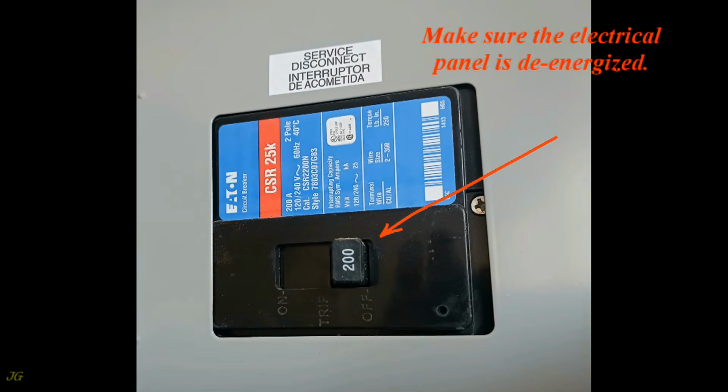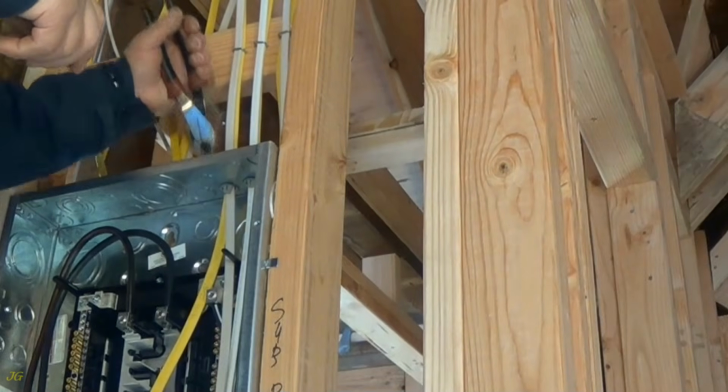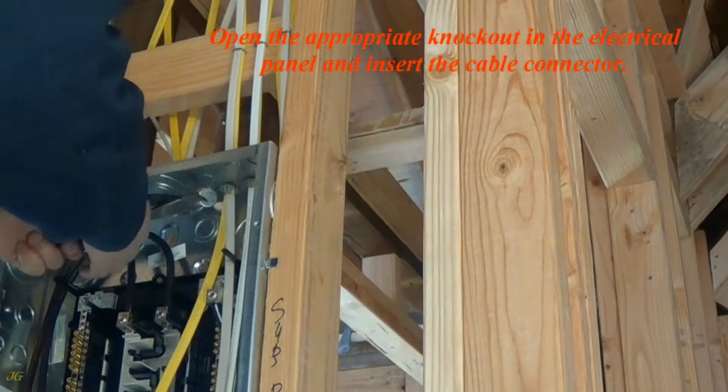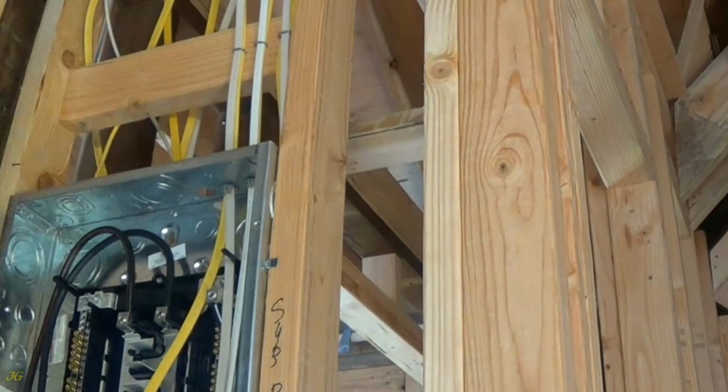Make sure the electrical panel is de-energized. Open the appropriate knockout in the electrical panel and insert the cable connector.